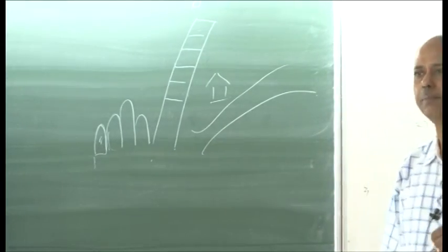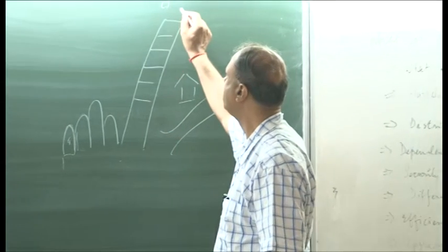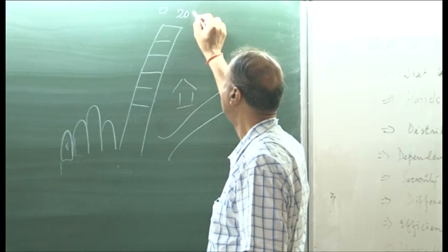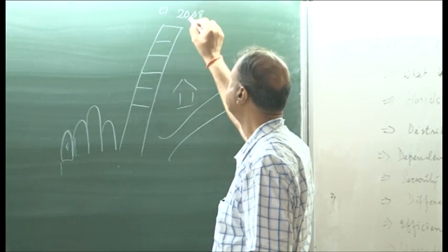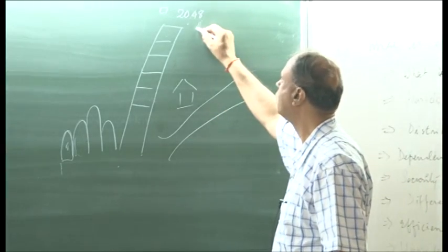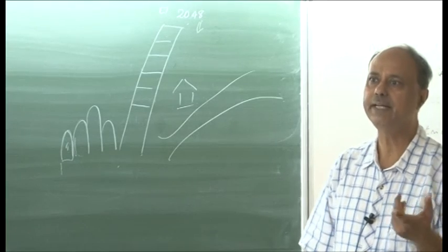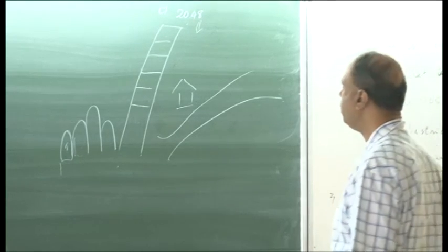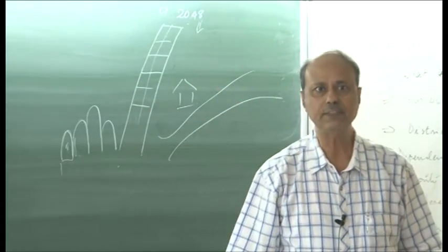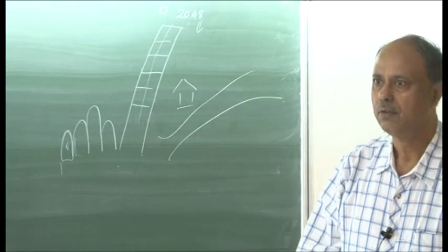It may so happen, suppose the satellite is CCD based, it has a CCD camera, say with 2048 CCD elements, and one element is not functioning well. It is not turning on and off. So what will you get? You will get one dark line, because that element will always not give you any image, since it is not on, right?